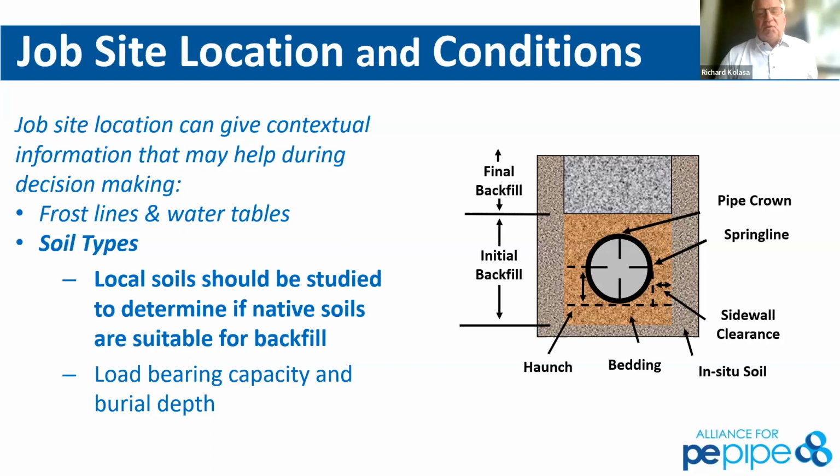Yeah, and we have to reiterate this quite a bit on the haunching and things like that, but that really locks that pipe in and really adds to the pipe stiffness. So you need to consider that backfill support, especially when you look at your H20 or H80 loads or whatever your dynamic loads are as well. And it may or may not change the DR that is applicable. So just always keep that in mind, that really adds a lot of support mechanism for the pipe.